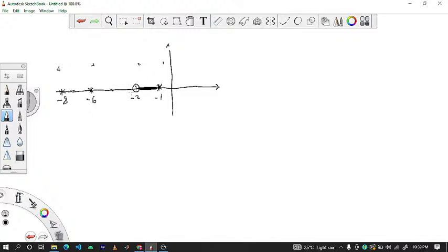This is an even number. So to the left of even numbers, there's no locus between them. So I'll go to the next odd number, that's 3, and then you draw a line to the left of 3. That's all. I'm saying this again: you number the zeros and poles together from your right. So I have element 1, element 2, element 3, element 4. Then you draw the locus to the left of the odd numbers. This is 1.